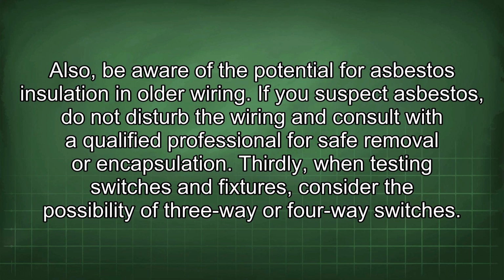Also, be aware of the potential for asbestos insulation in older wiring. If you suspect asbestos, do not disturb the wiring and consult with a qualified professional for safe removal or encapsulation.